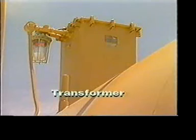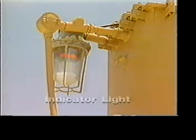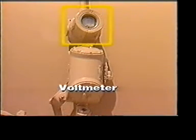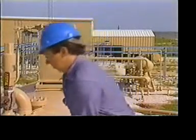On the electrostatic treater, a transformer will be used to step up the incoming voltage to power the electrical grids. Located on the transformer is an indicator light, which burns as long as the grids are working correctly. Connected to the transformer is the voltmeter, which measures the voltage of incoming electricity. And finally, a circuit breaker protects the transformer from power surges.